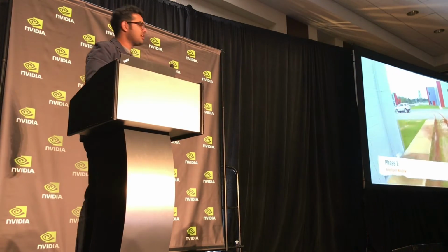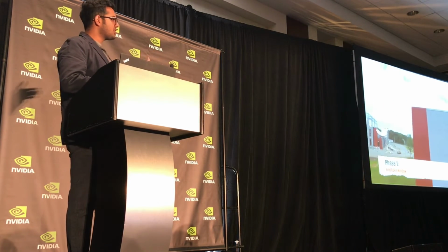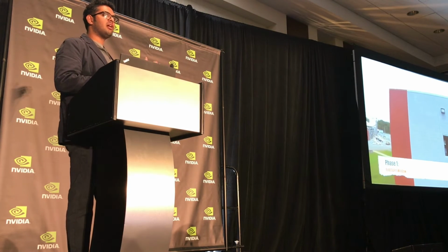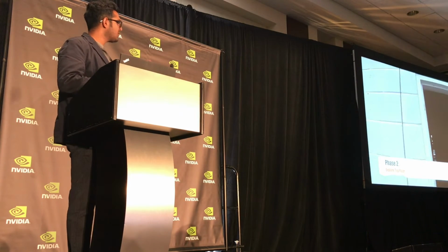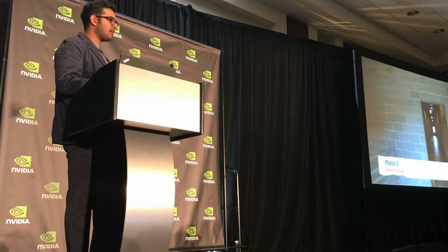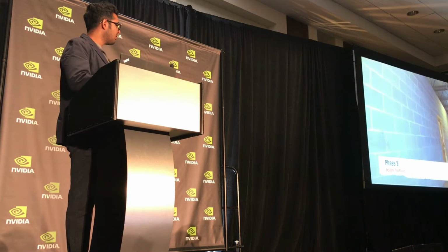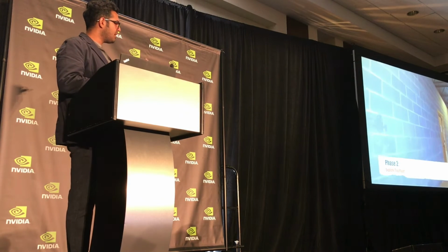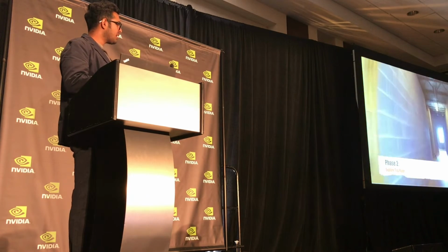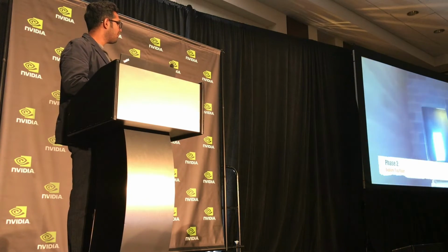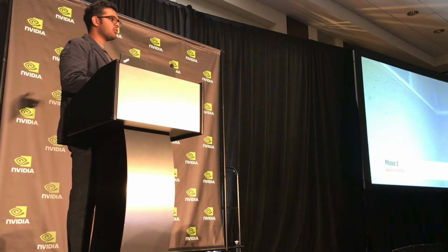Right, so this is the entire phase of our final mission for the Tampa FL challenge. So all you had to do was give the drone a very high-level goal, saying you're starting from here, you need to go to this location free of GPS. It's the building, wherever the final endpoint is, 100 meters ahead of you, and at some elevation if you wanted it to enter through a different floor. So here we gave it a waypoint inside the first floor from outside, just by guesstimating 100 meters ahead and possibly 20 meters in elevation, and the drone entered by detecting which window was open,